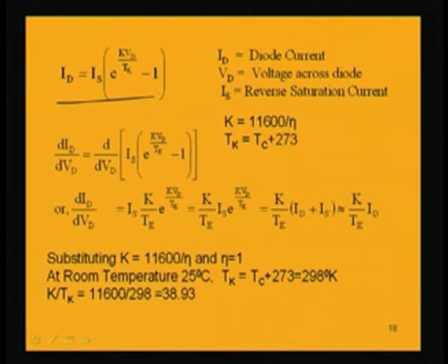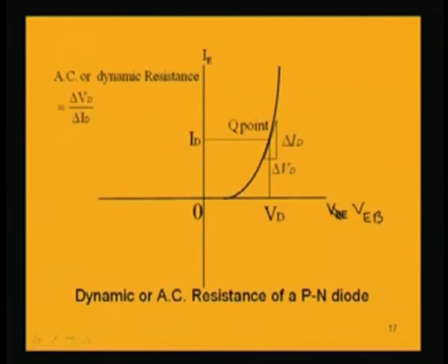If we consider the higher region or active region, eta both for silicon and germanium will be only 1, value 1 for both germanium and silicon, and for the higher portion or active portion, this linear region of the diode, eta value is 1.